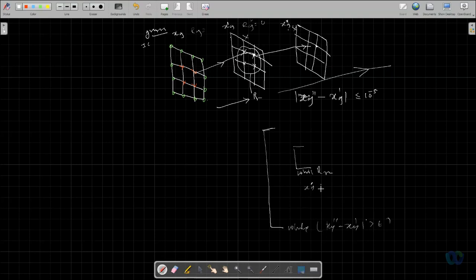So something has to be related to the program. Are you getting this or not? For unsteady it's okay, but for steady, this is also an iteration loop, right? If the residual condition is satisfied in the second loop, if the residual is falling to zero, then it means all the xg prime values you got are the correct values for that iteration. Now you have to check whether you have reached steady state or not. Shall we move to the next iteration? The values will change. For the next iteration, the xg prime values will become guess values. With these guess values, you will calculate new values again. But the residual will already be less than epsilon.